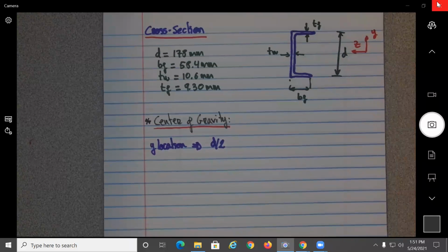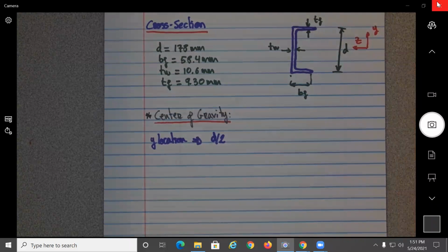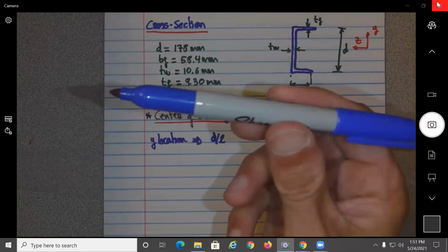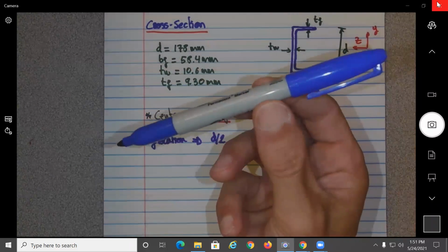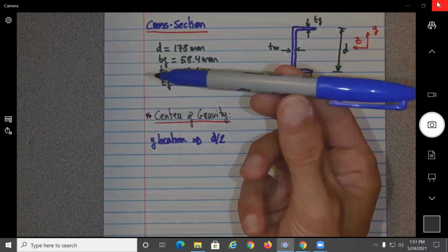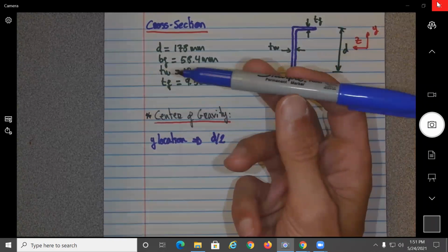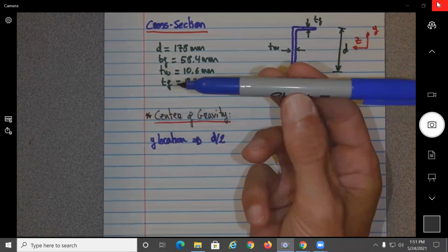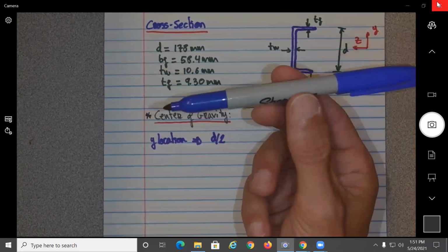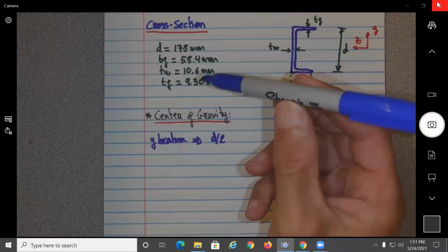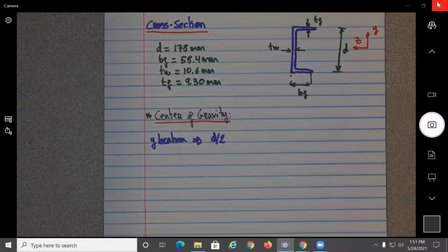All right, I know you all know that stuff, but when you need to do it, then it's a different story. How do you find the center of gravity of this marker? You start putting your finger at different locations until what? Is balanced, no? You do it until the location where there is no more rotation, correct? So you think about it, the CG is the point where there is no rotation.